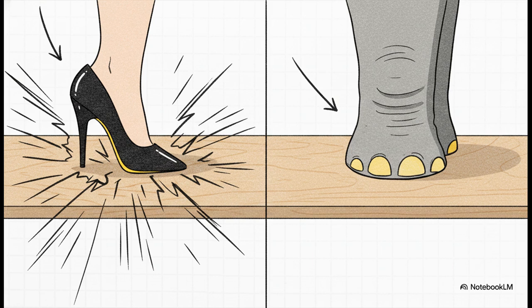And here is the grand reveal. A standard dance floor surface actually breaks when it hits pressures over 5 million pascals, or 5.0 megapascals. Since our lightweight dancer is generating 6.0 megapascals, they will literally puncture and cause way more localized damage to the floor than a heavy elephant. The elephant's wide feet keep its ground pressure safely below that breaking point. Honestly, this is exactly why some dance halls strictly ban stiletto heels. Sorry, fashion lovers, but physics always wins.